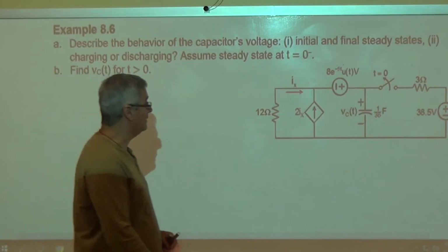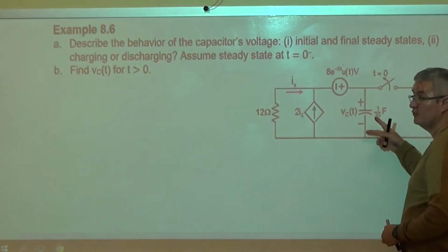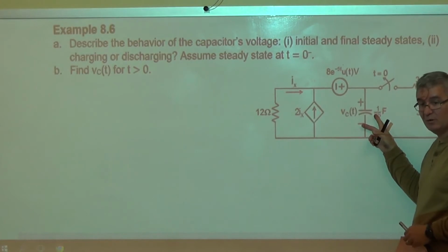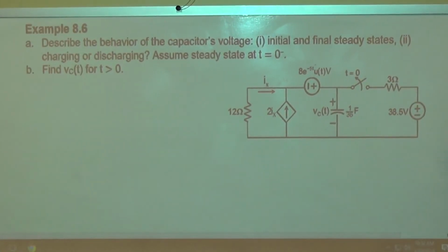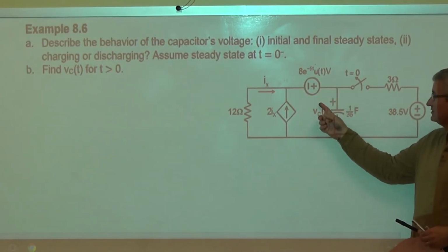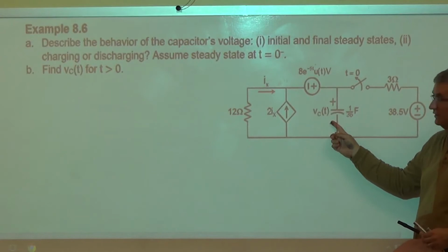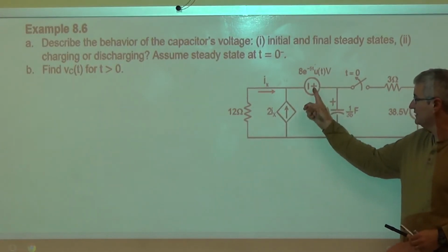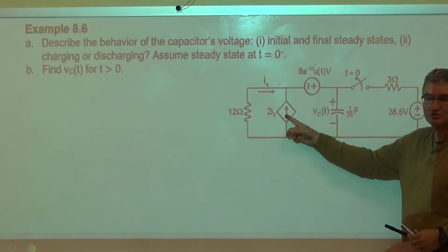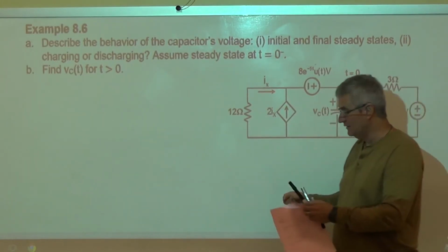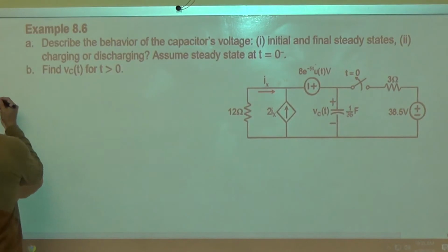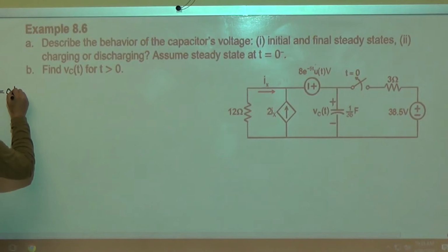Right? And it should be an open, of course, but it should go to 0. Because think about it, the only active source that's constant is being what? Taken out of the circuit. And because this is taken out of the circuit, this will give it a burst for a brief amount. But then that Ix, because nothing is resupplying this thing, goes to 0. So immediately what we're seeing in this circuit is that at VC t equal to infinity, it should go exactly to 0.